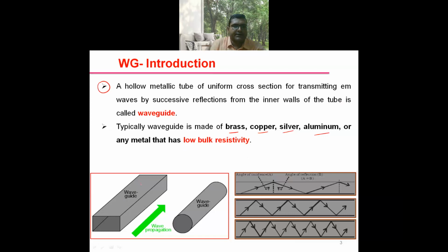It is a rectangular waveguide made with a good conductor, meaning the conductivity of the walls is equal to infinity. It is a hollow conducting tube. The space inside the waveguide is filled with a source-free lossless dielectric material. The conductivity is zero inside the waveguide.